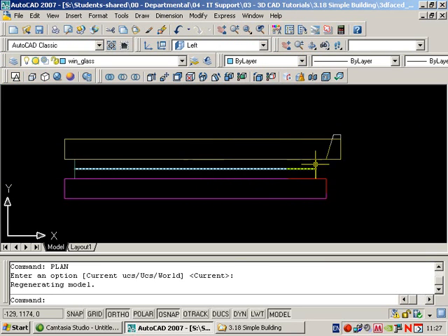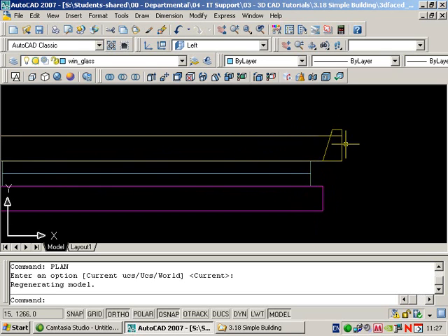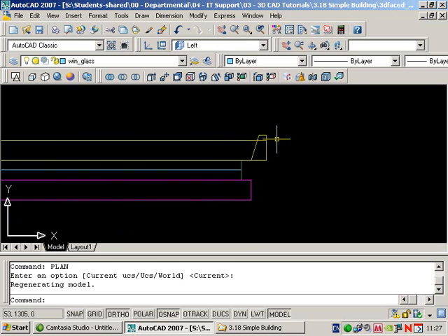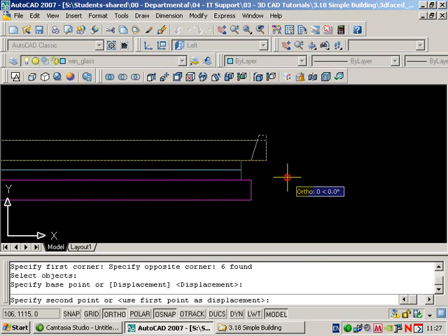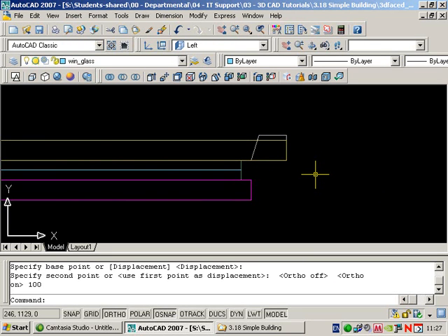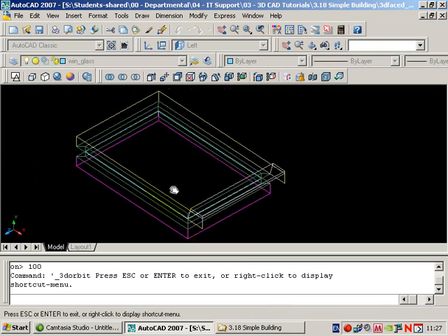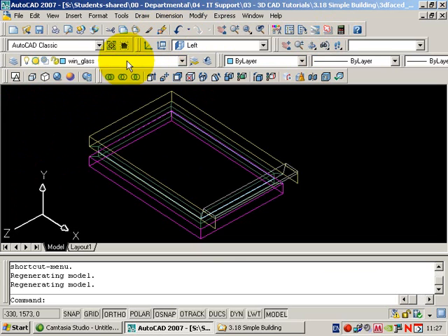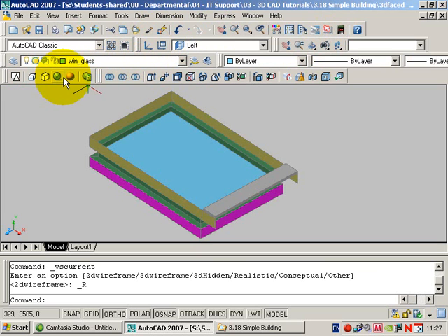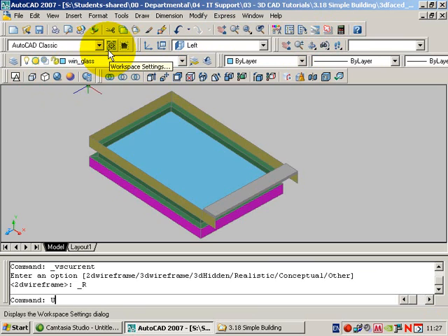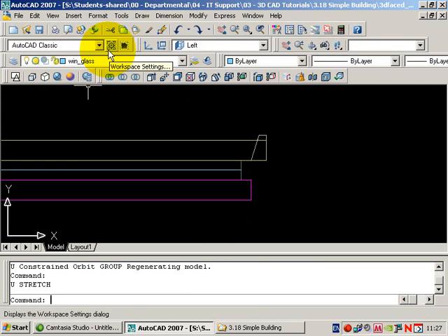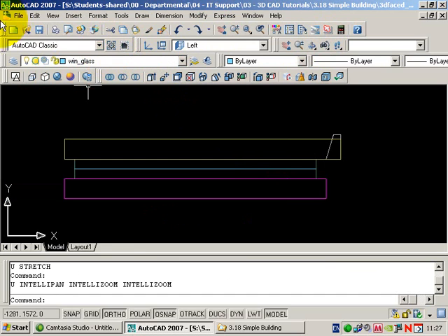But you can see that the window reveals, internal window reveal will be higher up than the external. That's to allow for the window sill. But creating it from 3D faces allows you to maybe modify the height of the sill. Could add another 100mm onto the sill. It's much easier to tweak kind of fairly complicated objects like windows if they're made out of 3D faces. Okay, your sills might extend outside the window.